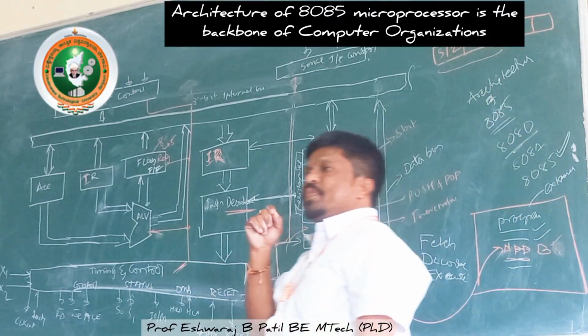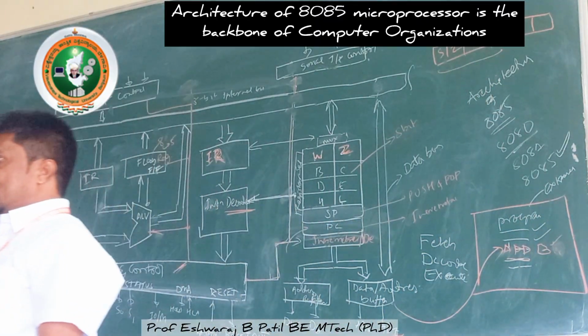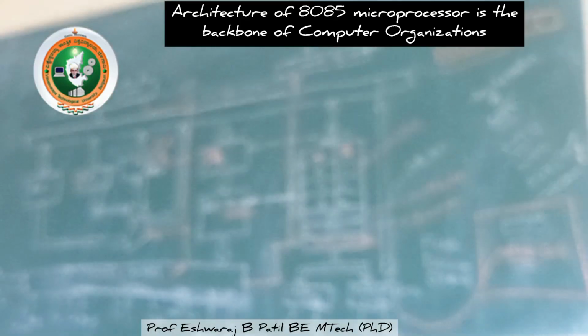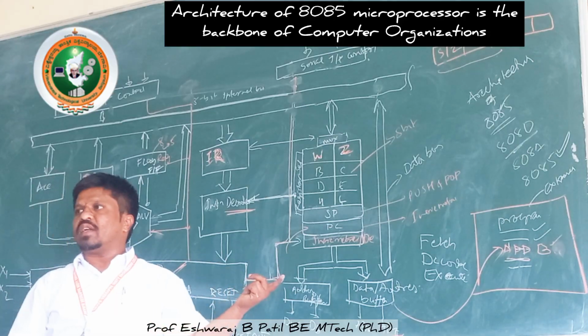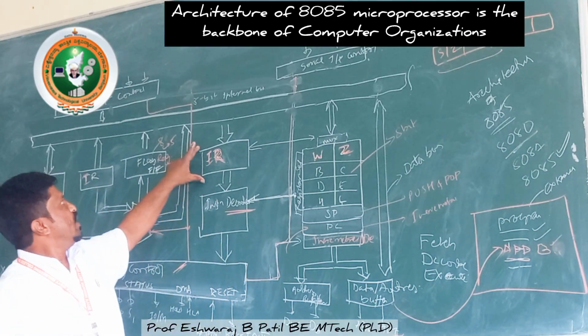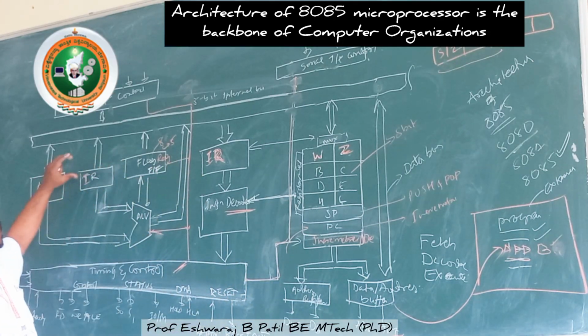This means these particular 5 flags will be raised. If the result is 0, the zero flag is raised. If it is negative, the sign flag is raised. If there is a carry from the 4th bit to the 5th bit, the auxiliary carry flag is generated. We will be raising them, and the answer we get will be stored there.